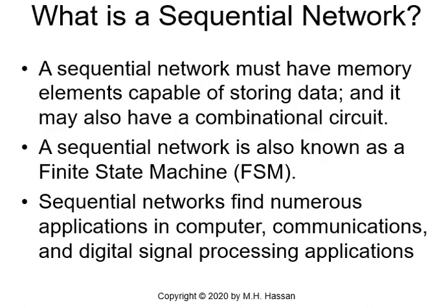And the reason behind this: if a network has n number of memory elements or flip-flops, the maximum number of states the network may have is 2 to the power n. For n number of flip-flops, the number of states will be 2 to the power n. For 3 flip-flops, the network may have up to 8 states, and so on and so forth.